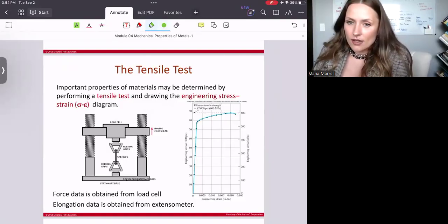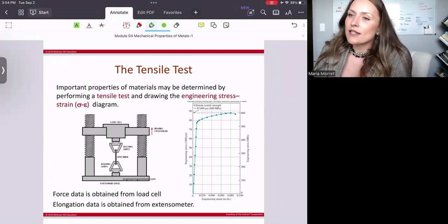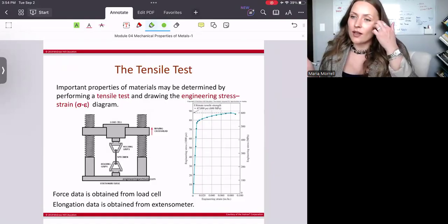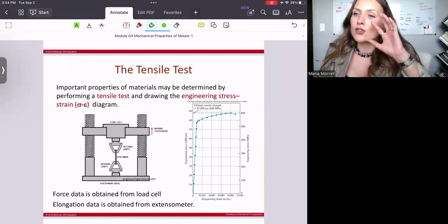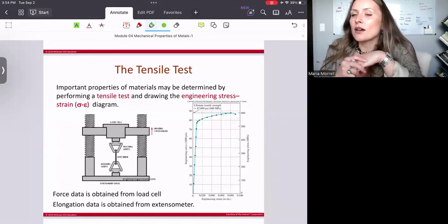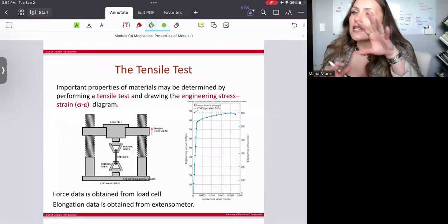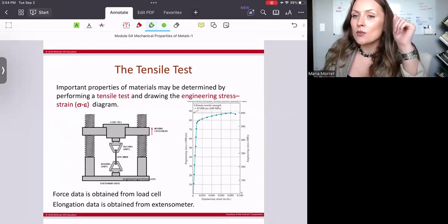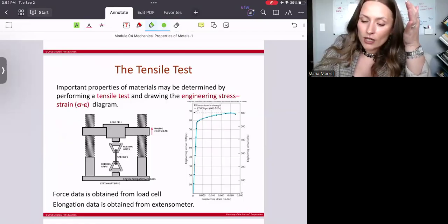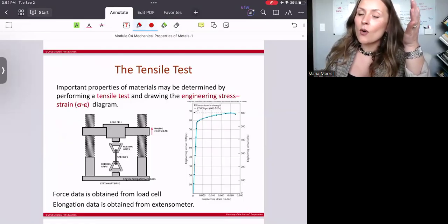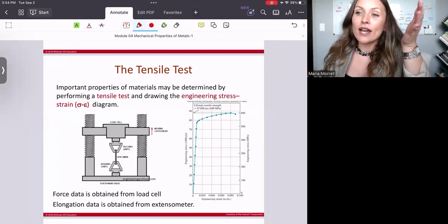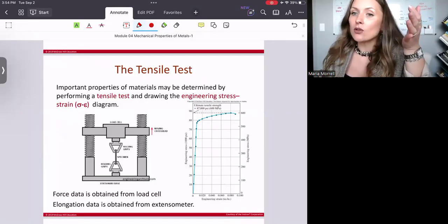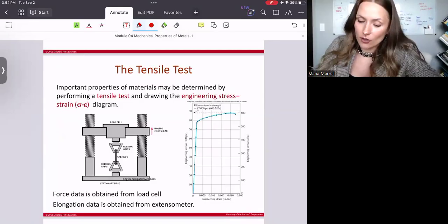Typically, for us to find out anything or perhaps everything about the material in terms of the strength, the ductility, the yield point, meaning when the material actually fails, we need to perform the tensile test. Or in a sense, for us to know mechanical properties of any metal or a metallic alloy, we need to conduct a tensile test, okay?